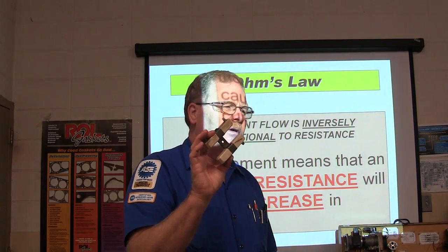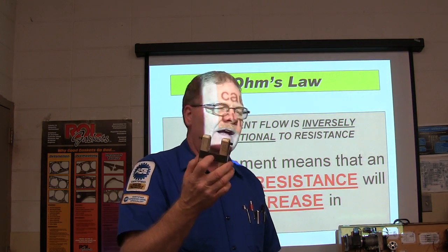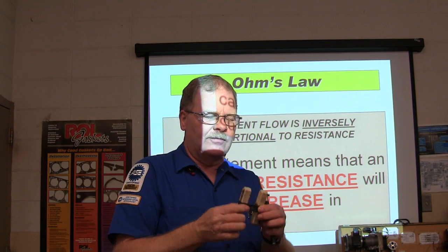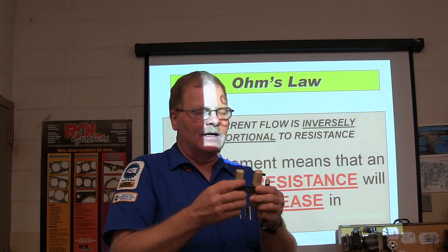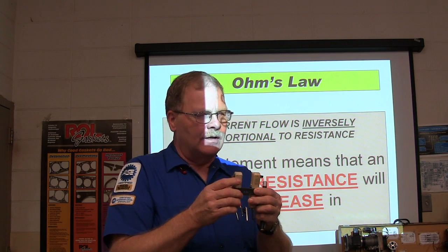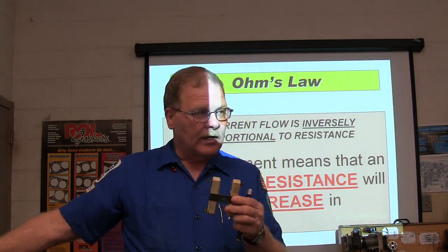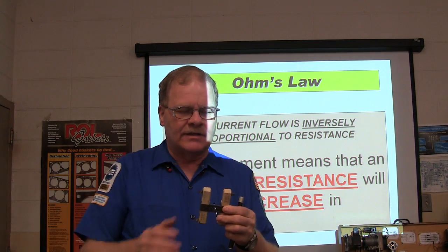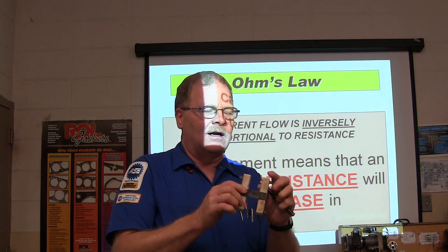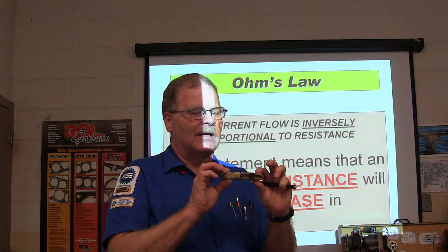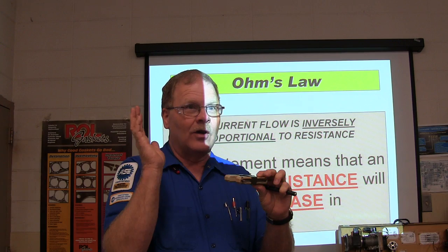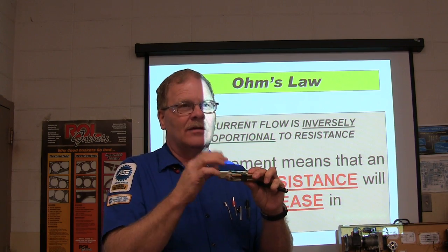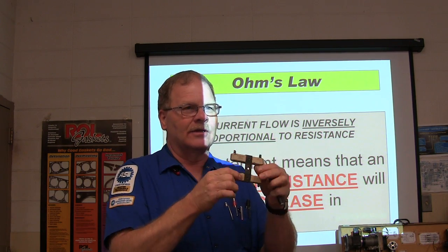Sometimes when you want to lower the speed of the fan, you run the fan through these, and it slows the fan down. There's no resistors on this board here, but we can run it two speeds by wiring them in series one way. These are heavy-duty ceramic, because if current is flowing through that thing and you touch one of them, you're going to know it. It'll lay a clear blister on your finger when these things are good and hot.